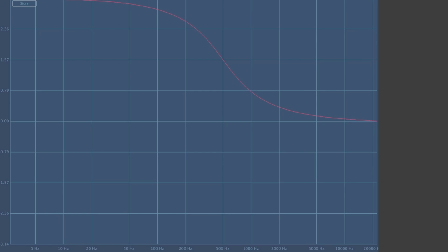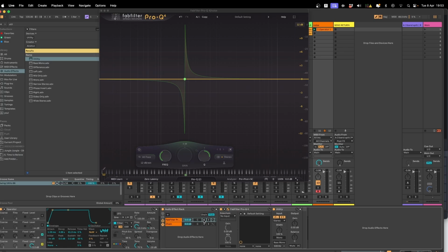The phase difference between all the harmonics, between all the frequencies, is not the same. This is how we can change the tonal balance with filters. Filters are, in fact, simply phase devices. Of course, there are linear phase filters, but let's talk about a traditional type of design. Many digital filters just mimic the same design and reproduce the same impact on phase as analog filters.